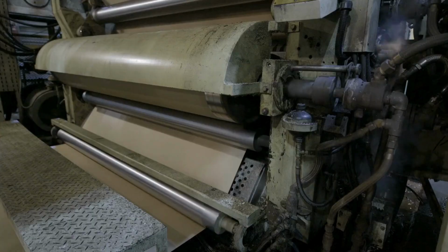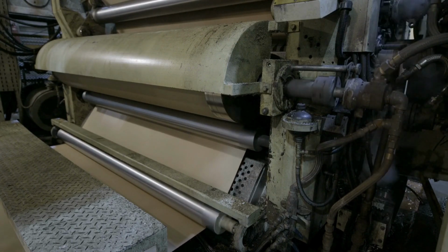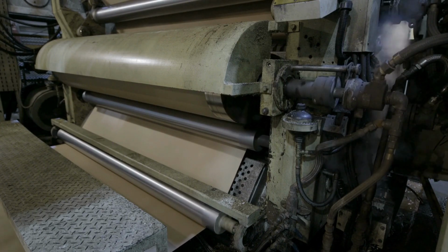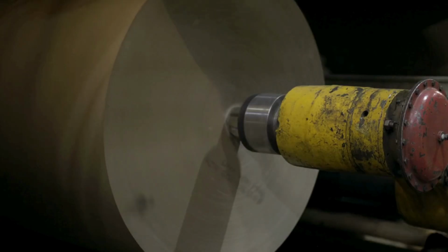The pulp slurry is evenly distributed onto a moving wire mesh, known as the wire or forming fabric. Water drains through the mesh, leaving a thin layer of fibers, and the fiber mat moves to a press section where rollers squeeze out excess water. The semi-dried paper sheet passes through a series of heated drying cylinders to remove moisture in the drying step. By the end of this step, the sheet is typically 94 to 96% dry.